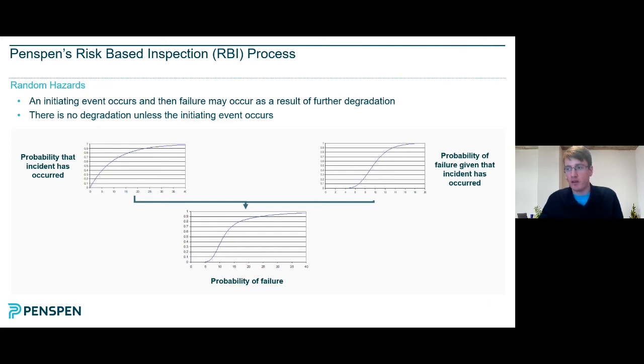In terms of the probability of an incident occurring in the first place, there's various industry failure data available that can be used as a baseline. In the UK, offshore there's Parlock, and more globally OGP has a similar sort of failure data set. Onshore in the UK, UKOPA retains failure data for onshore pipelines, and similarly in Europe there's EGIG and CONCAWE data sets. So we can use these as our first point of determining what the potential for some kind of impact damage being, and then we can modify this if sufficient company specific data is available, or even, depending on how long an asset has been operated, asset specific data.